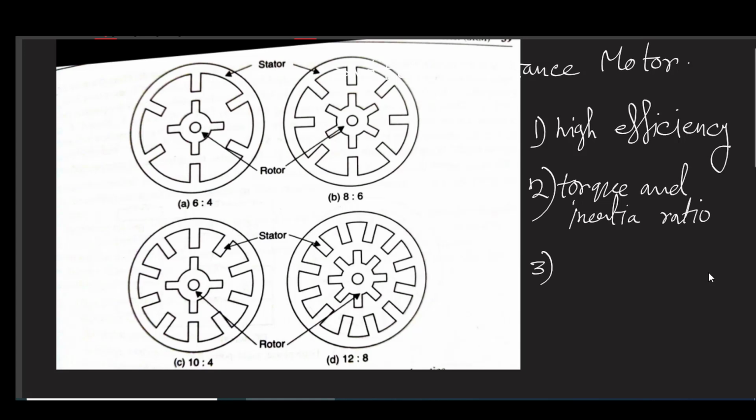Generally more inertia means higher dimension, since we are generally working with materials whose density is quite common in most cases. So if you are going for a heavier machine, you are bound to occupy more volume. And also there are machines where weight is a constraint. Space and weight of the machine, meaning how bulky it is and how much it weighs, is a very crucial question in case of a small scale application.